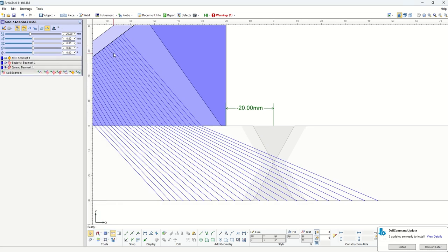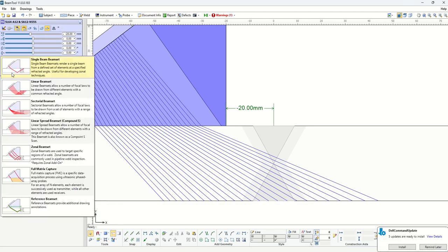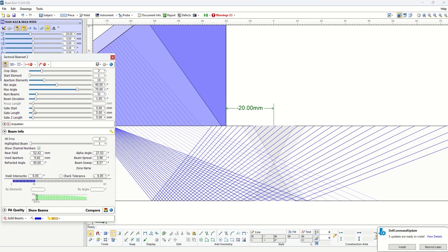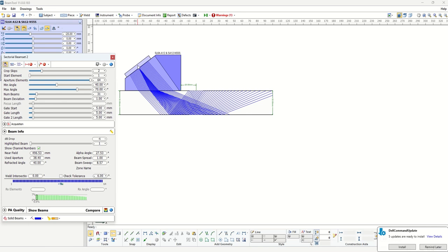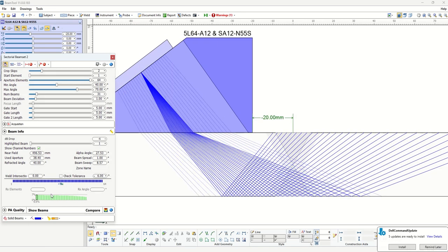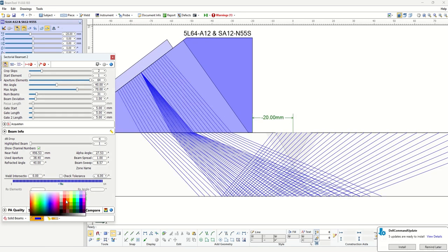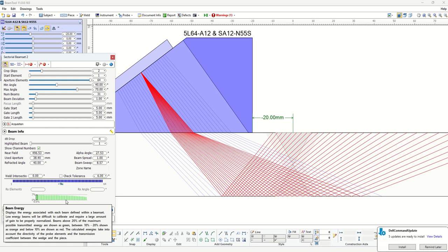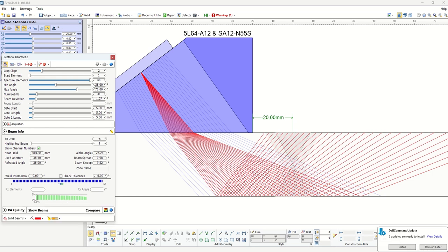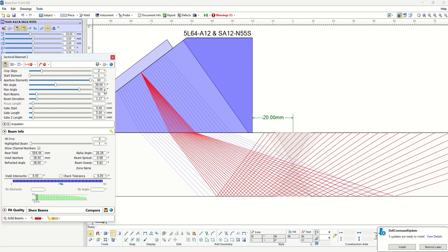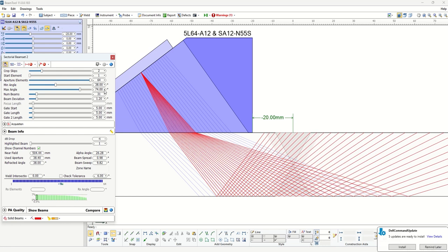But the point is, now if I come here and add focusing, let's say we come to a sectorial scan, and if our instrument allows, we use all 64 elements in the aperture. Now I create a similar beam set, but this time with 64 elements. So I can come to lower beams here and much larger angles to cover my bevel.